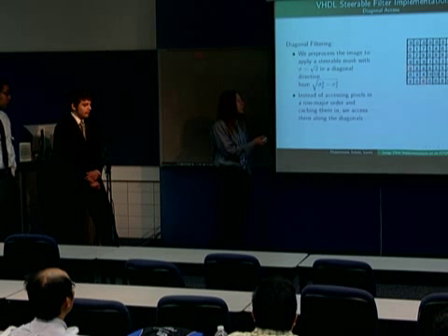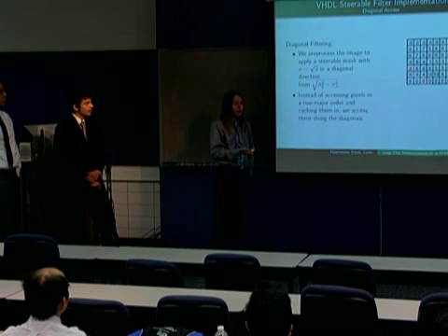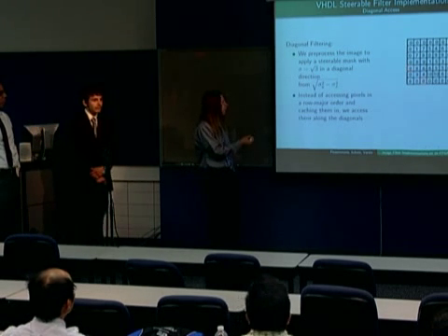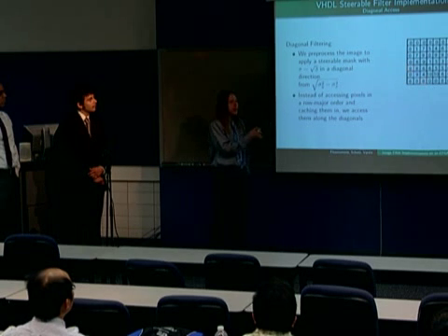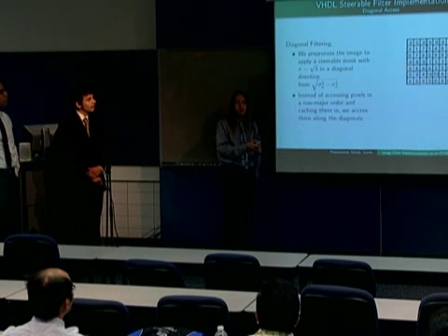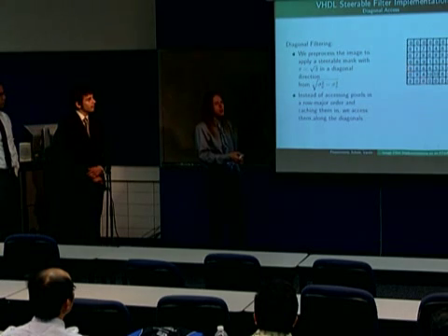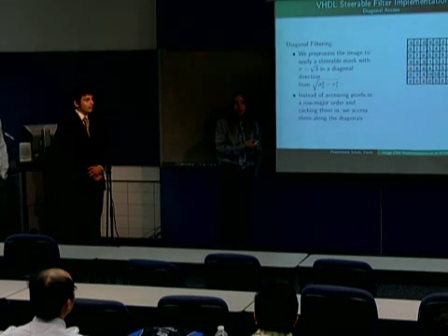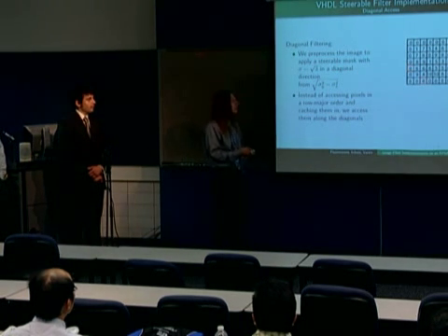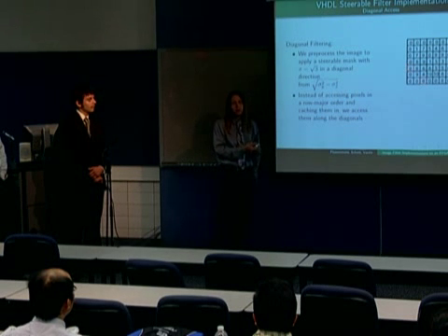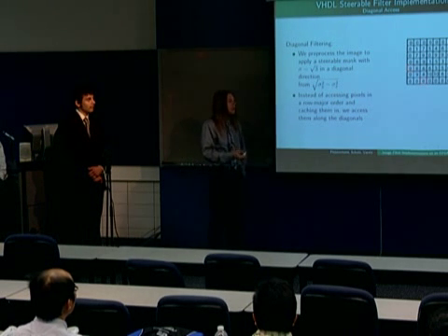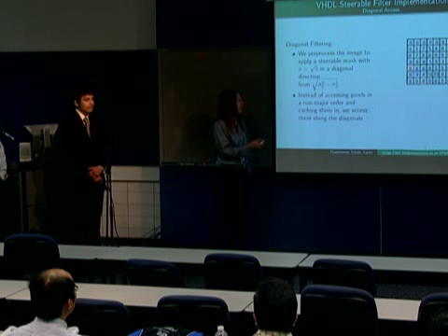And this is beneficial because the way that our module works, you populate it with pixels, and then when you get to the next row, you have to get enough pixels yet again to do the correct convolution, because the bandwidth of our BRAM is only 1 pixel per cycle. That could be fixed by using RAM and other things, but we decided to exploit it for our design.